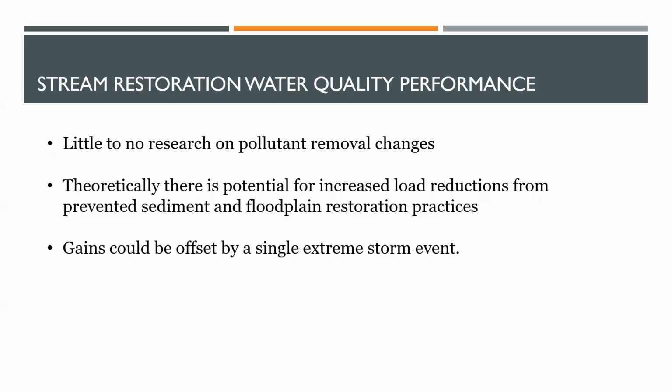Theoretically, there is actually potential for increased load reductions based on the stream restoration protocols. Because those protocols are based on a change from pre-restoration to post-restoration conditions, if you think about it in the sense that higher flows, more intense flows are likely to increase bank erosion rates before restoration, worsening the conditions of some of these streams in the short term.